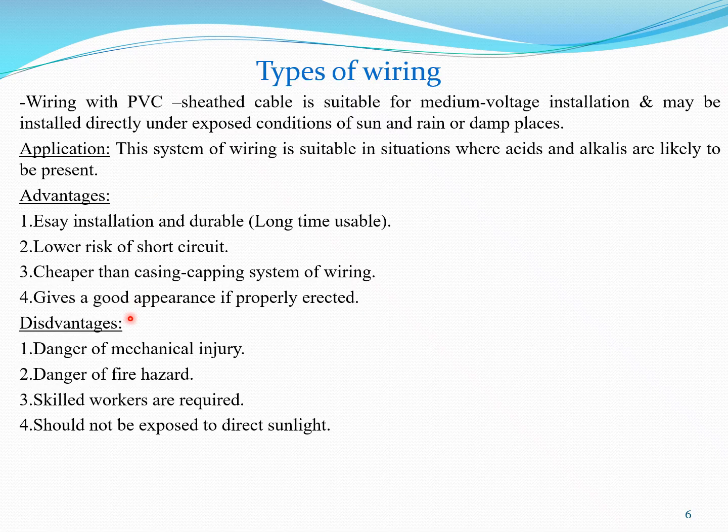What are the disadvantages or limitations of this wiring? First one, it has the danger of mechanical injury. Then there is danger of fire hazard. Then for this type of wiring, skilled manpower is required and it should not be exposed to direct sunlight.